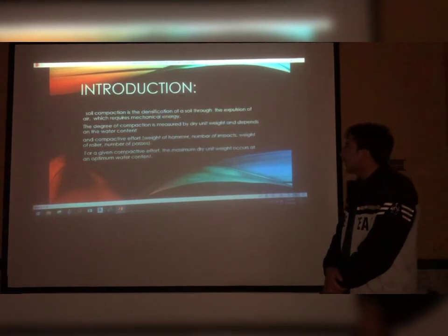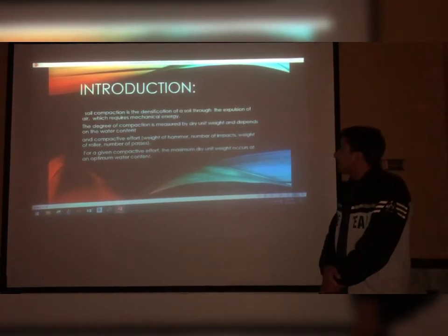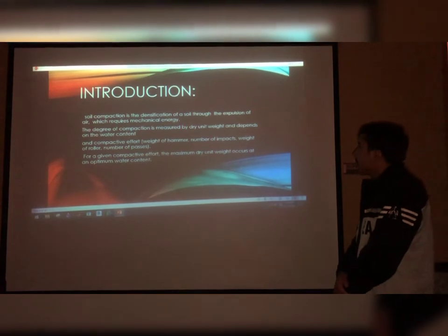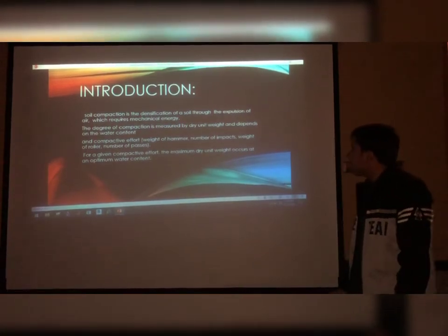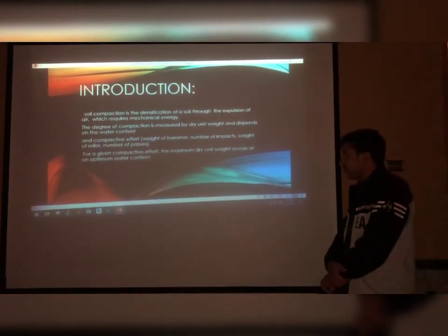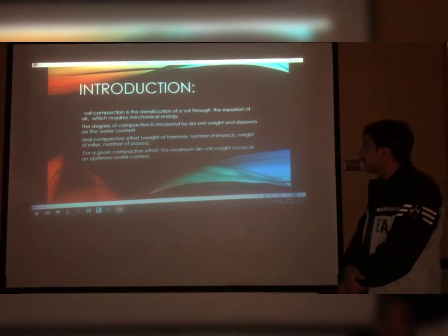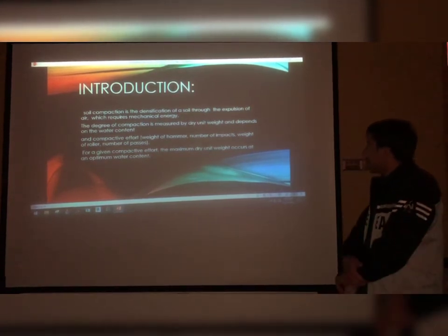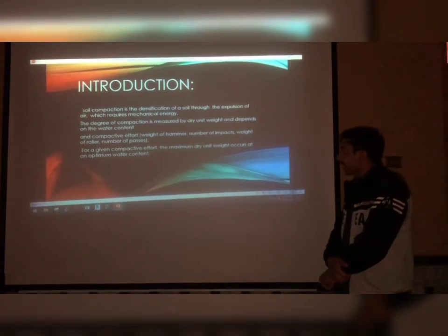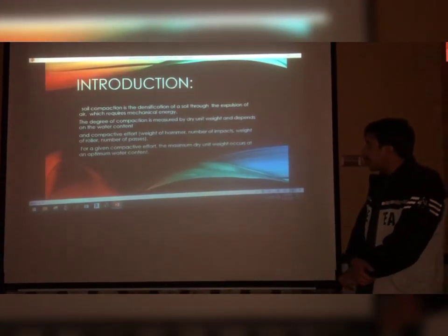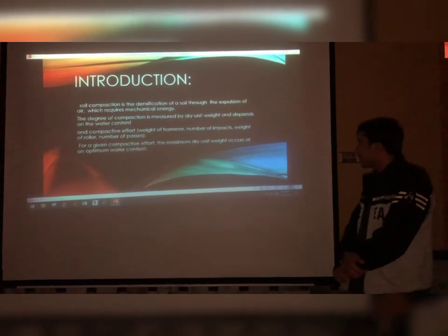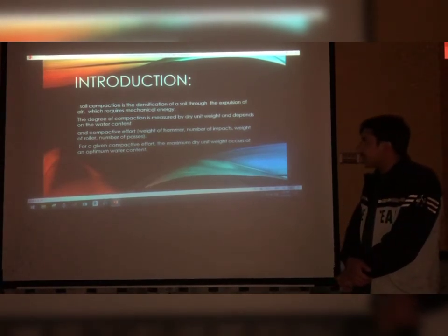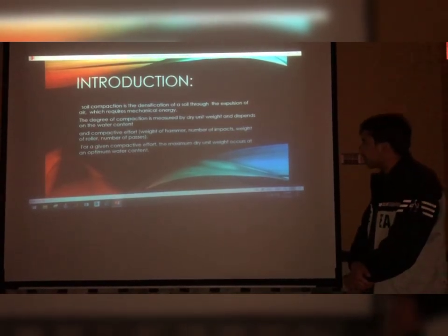Next slide. First, we will introduce what compaction is. Soil compaction is the densification of soil through the expulsion of air, which requires mechanical energy. The degree of compaction is measured by dry unit weight and depends on the water content and the compactive effort. What is compactive effort? Weight of hammers, number of impacts, weight of rollers, and number of passes.